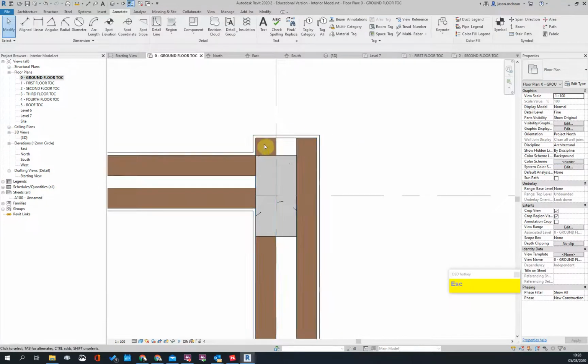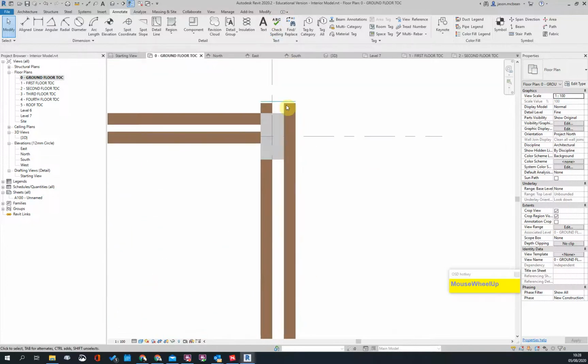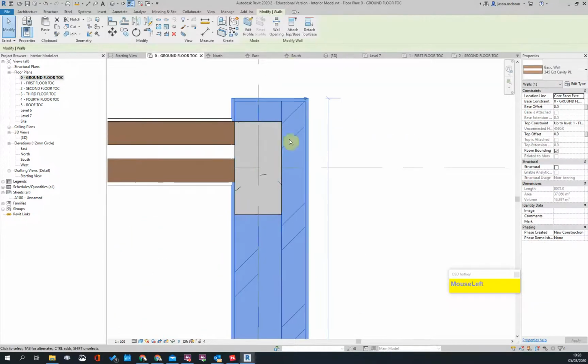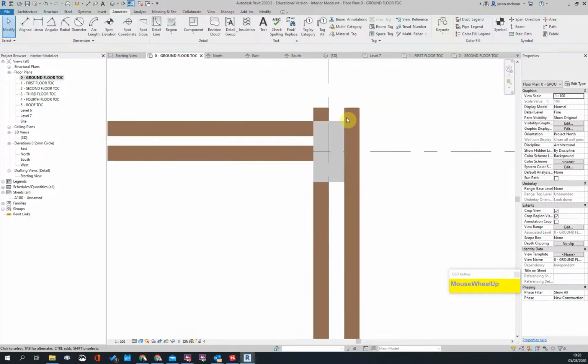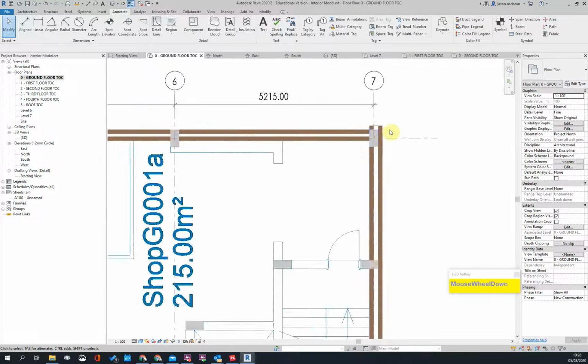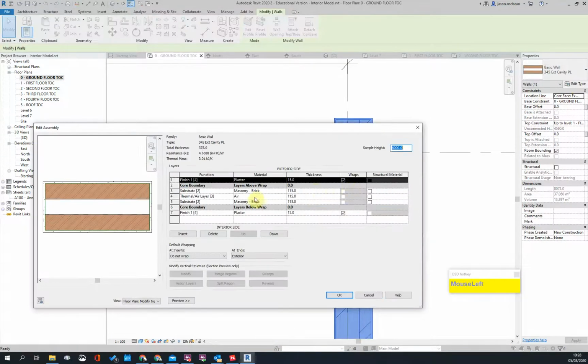This wall also ends differently, so it won't end in the cavity, it will end in the solid, but that's fine. I mean, we can change how that looks at the end as well. We can wrap the masonry. Those get tricky, but for now, in a nutshell, I'm happy with that. Okay, so if I go to edit type, you'll notice that it won't allow me to wrap.